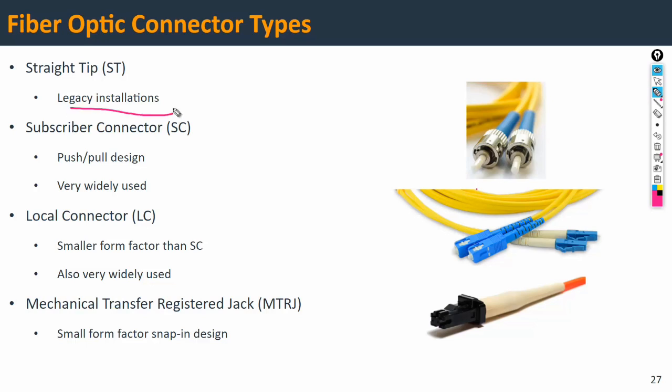If you want to do the basic installation, then you can use the straight tip, or it is called the ST connector. There is another connector, called the subscriber connector. It is designed for push and pull, and it fits into the connector, and this is very widely used. Everywhere you can see this type of connector being used.